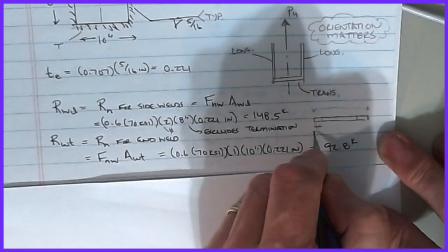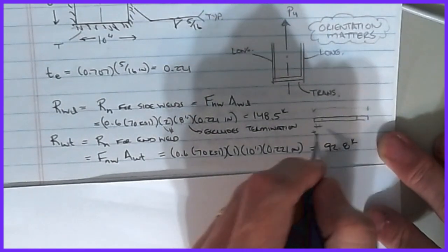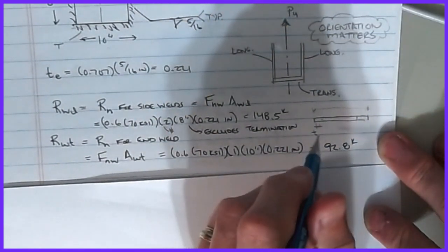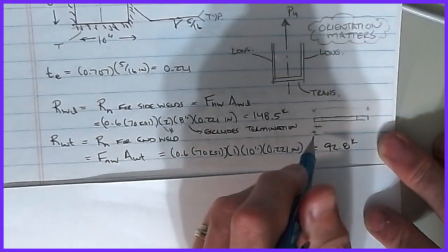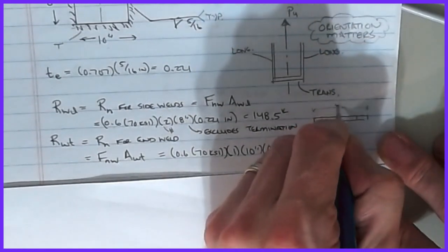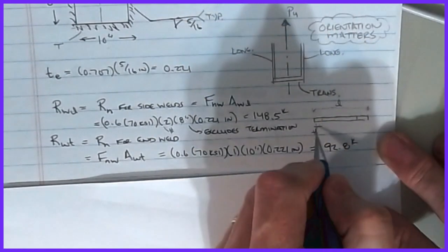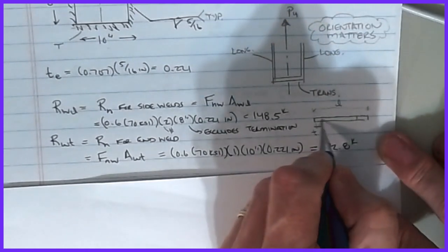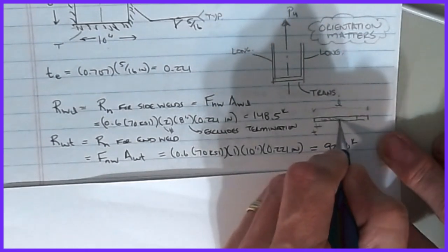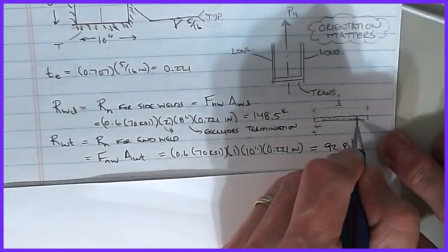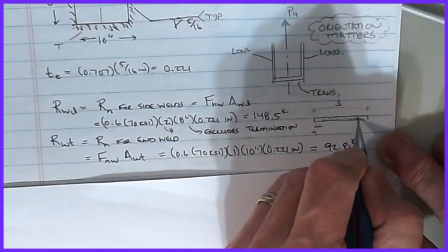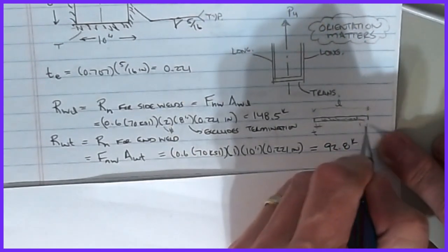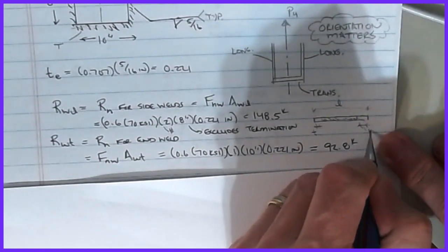So often you discount that, generally related to the thickness of the weld, out of the overall length. So we said the overall length is this. You start here and you start welding, and by the time you get to here, now the weld's good. Then as you get close to the end, your hand starts to lift up and you have a similar problem on the back end. This is what we mean by terminations.